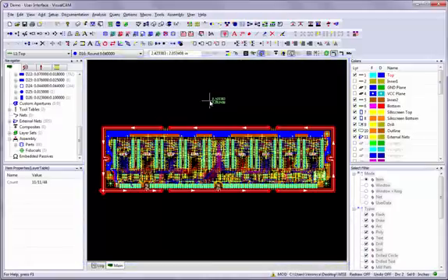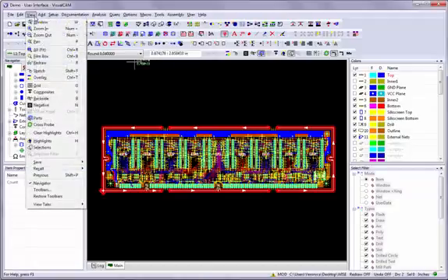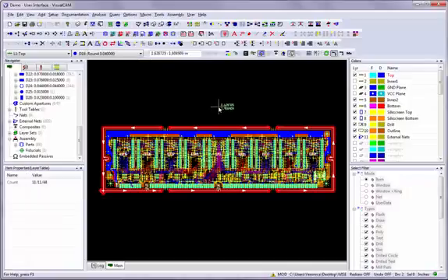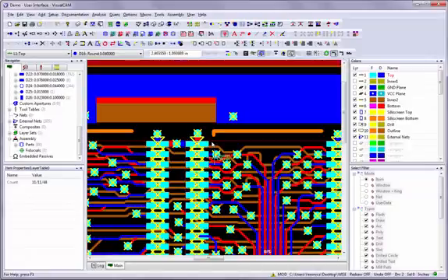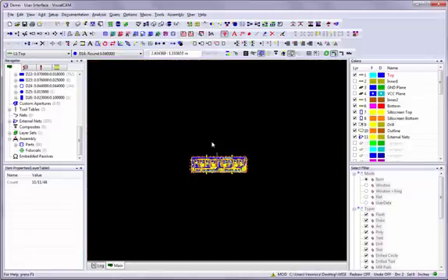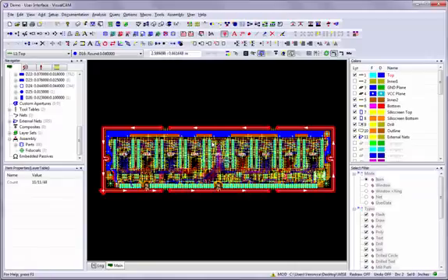The workspace is where the graphical representation of your database appears. The commands in the View menu and their associated toolbar buttons control your view of the workspace and allow you to edit the data. Learning some commonly used keyboard shortcuts is always beneficial. With the pointer located in the workspace, press the plus key on your keyboard to zoom in on your design, the minus key to zoom out, and the Control R keys to fit the design to the size of the workspace.